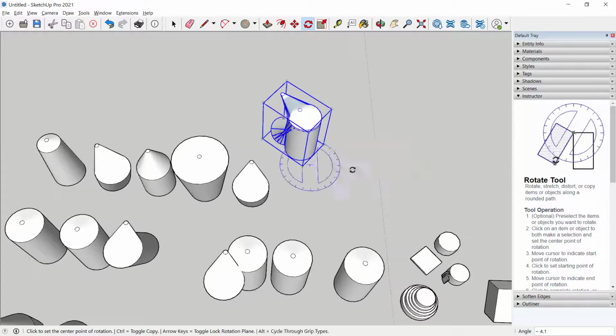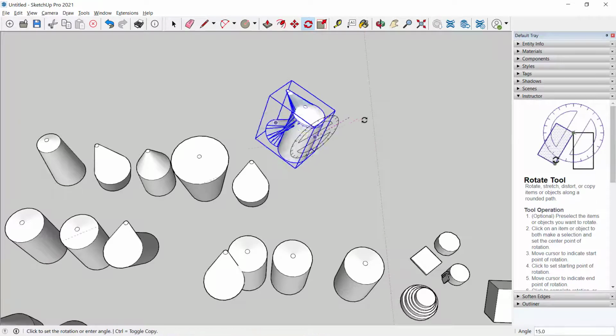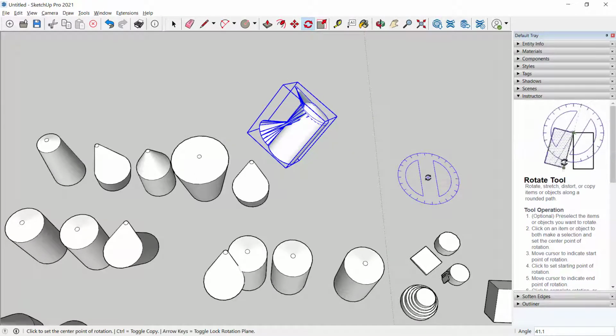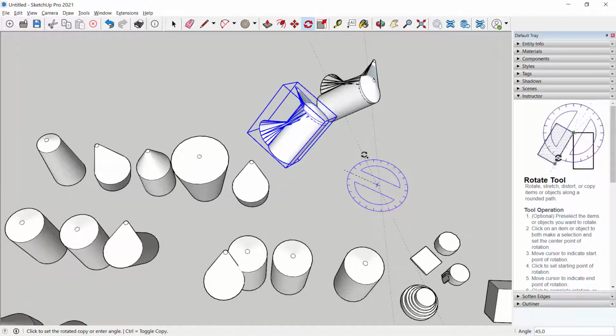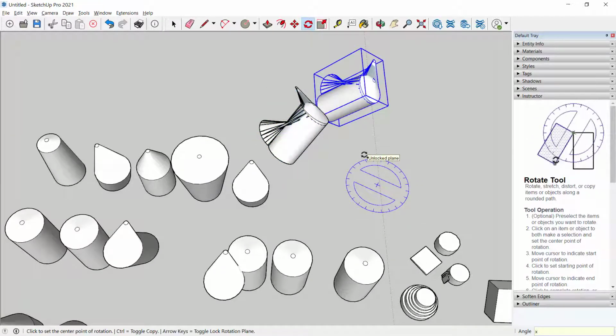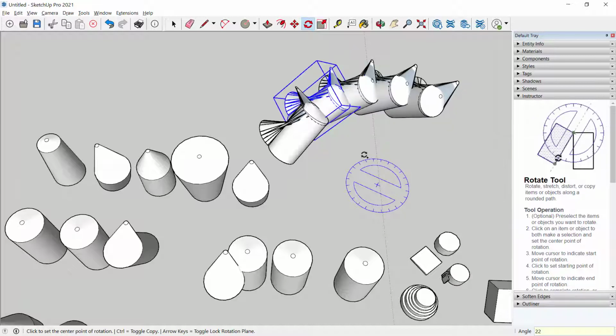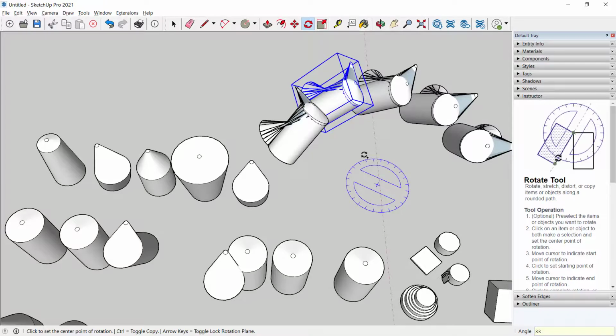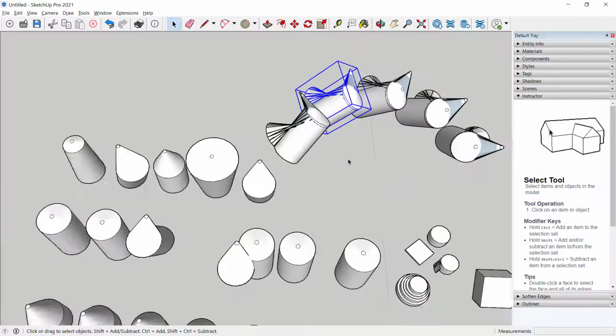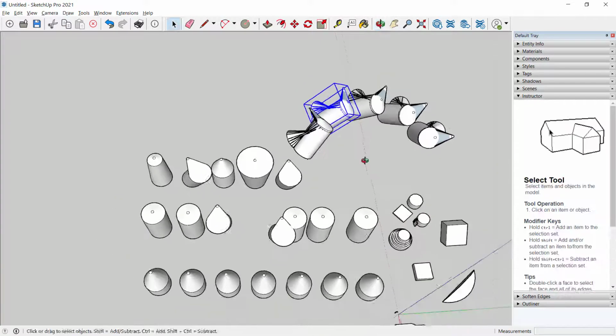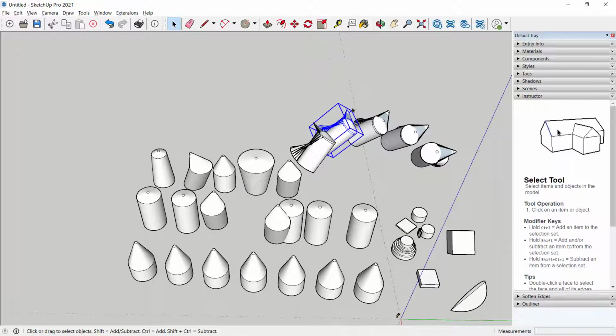And you can put that protractor on any surface. So for example, I can rotate this in the vertical dimension. The other thing is you can tap Control and make a rotated array using that same X multiplier. And there we go. I can change how far apart they are, and even the number of degrees apart by typing in the number. So there are all sorts of interesting things that you can create using that rotated array.